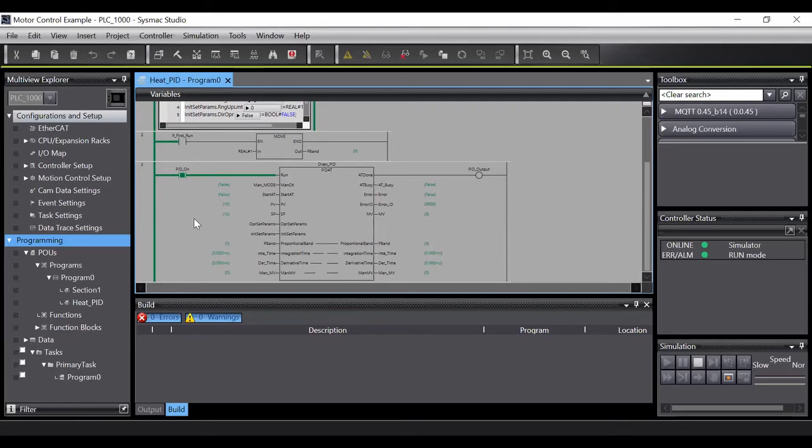Okay, so you should have some output now, but you don't. Your P band is 0. So just change that to a 1. You can just double click on it, and hit enter. Now retoggle your loop, just change that off and on. Okay, now lower your set point to 5 or so, just so it wants to increase its output. Interesting.